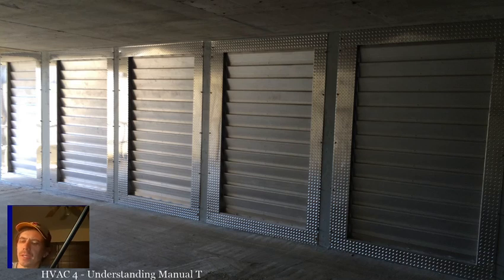The other thing to keep in mind, especially with condos, if you ever work in condos or commercial buildings where it penetrates a firewall, there'll be fire dampers a lot of times off of the furnace, and if the furnace is overheating, it can get those fire dampers to close.